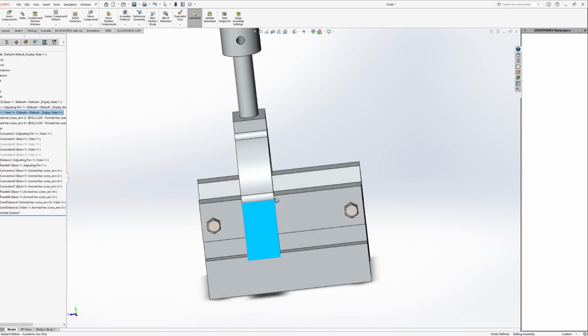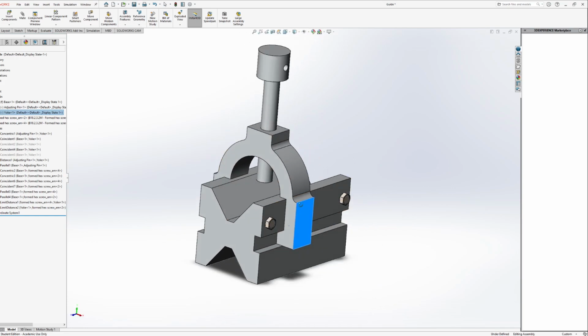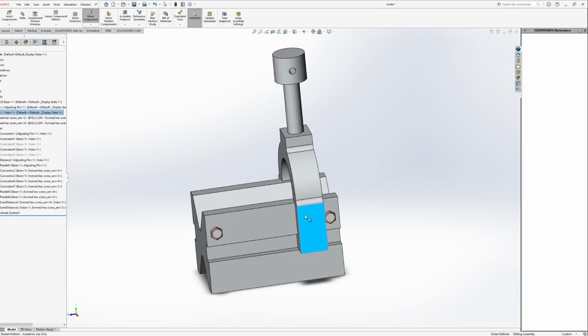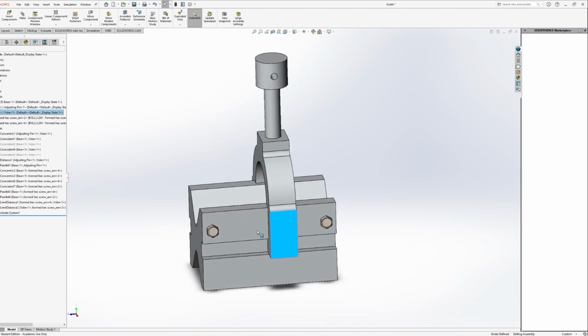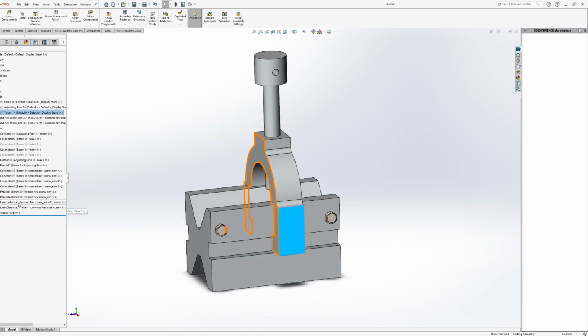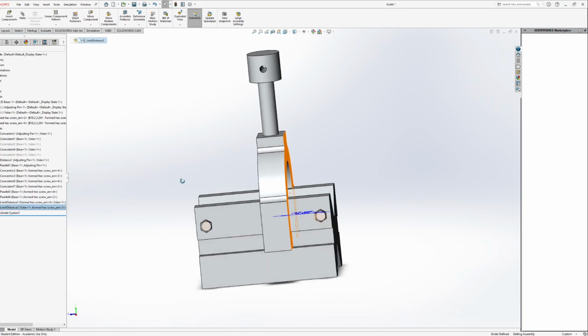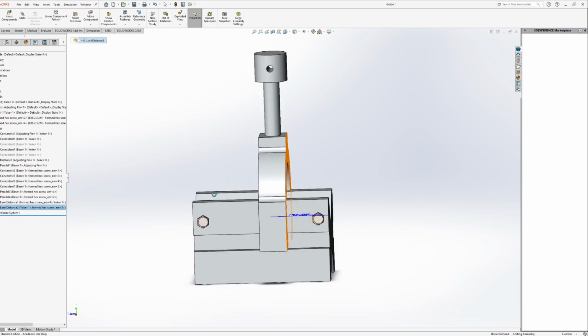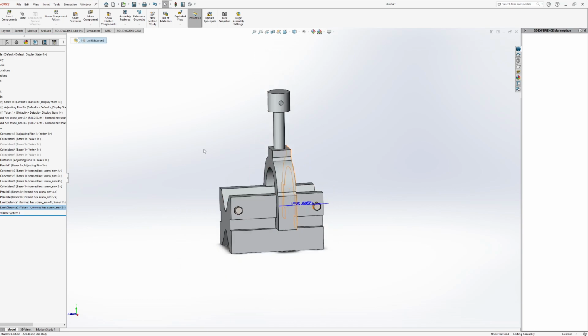So I think the end all be all, or the basis for what I'm getting at here, is that you don't need both of them. You only should have a single limit distance from a given reference point, or else you're going to have both of these limit distances fighting each other to try to get a correct measurement for where the yoke and the adjusting pin should be.